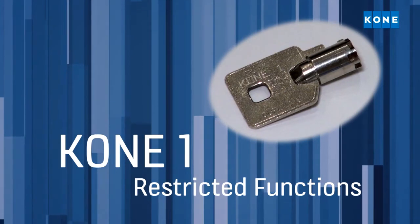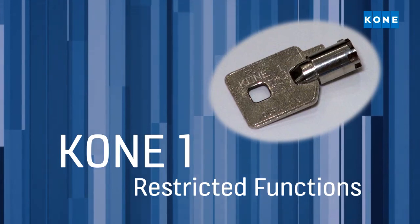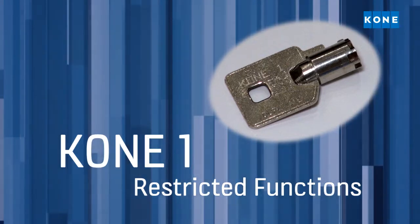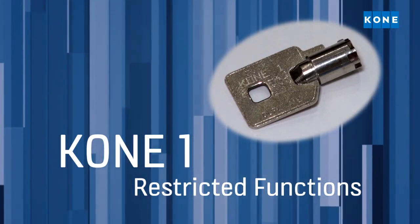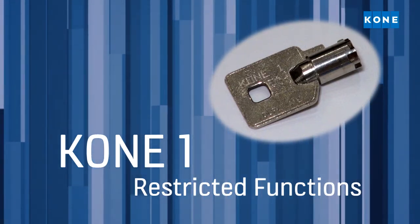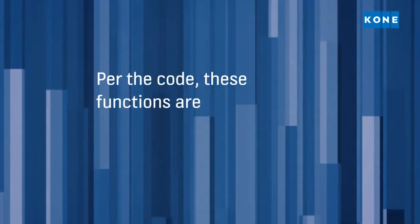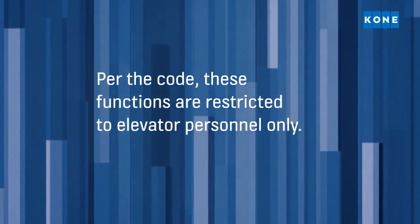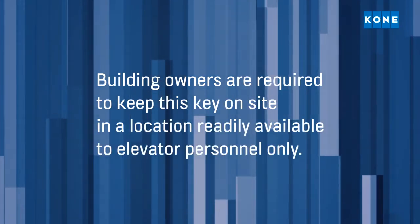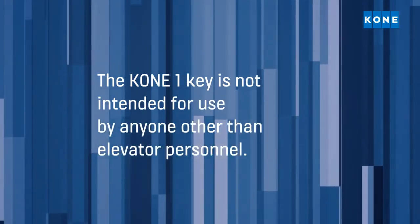The KONE 1 key provides access to functions that are a subset of Group 1 security as described in ASME A17.1 CSA B44 Section 8.1.2 from the year 2000 onwards, including the in-car stop switch, hoistway access, and, if applicable, Integrated Control Solution or ICS access panel. Per the code, these functions are restricted to elevator personnel only. Code requires building owners to keep this key on site in a location readily available to elevator personnel only. The KONE 1 key is not intended for use by anyone other than elevator personnel.